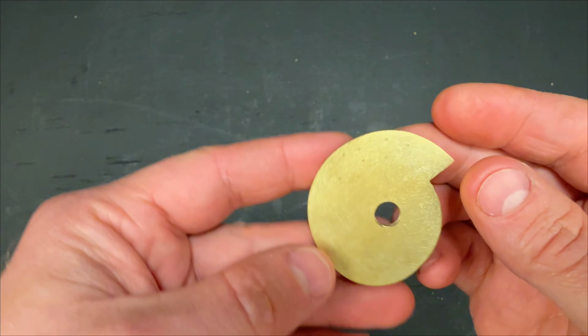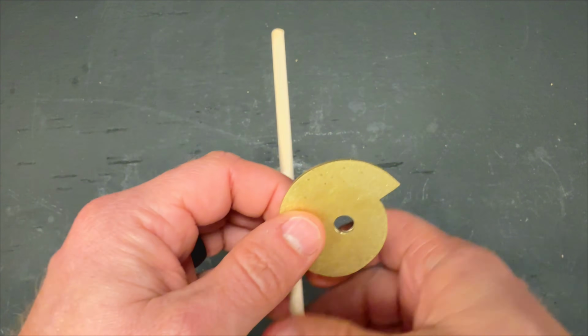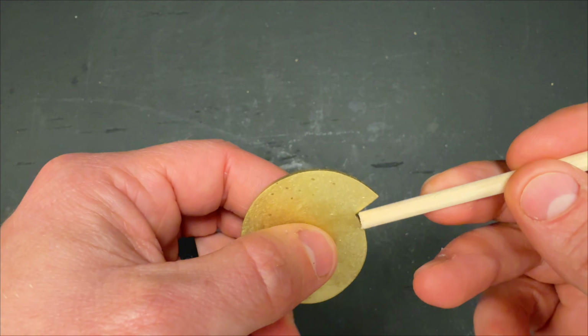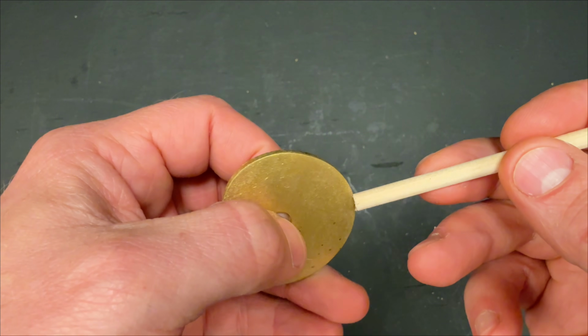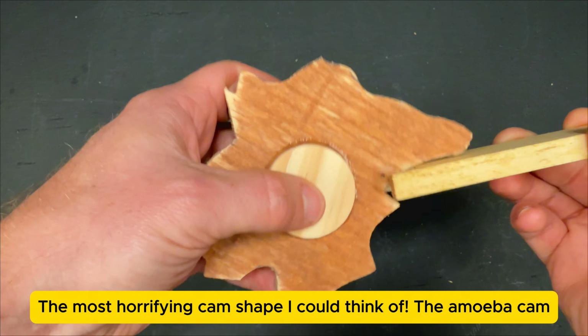The path the follower should make must be reverse engineered by carefully considering the desired end result, and then engineering that exact shape that will, when rotated, play back the correct combination of movements against the follower. Too many sharp angles on the cam and the follower will get stuck.